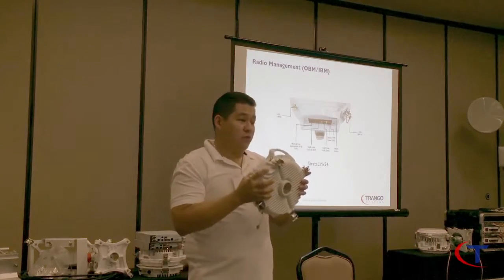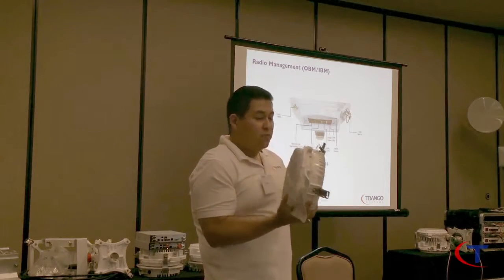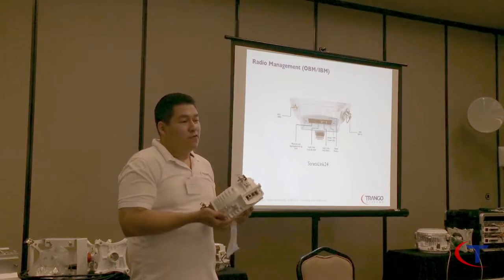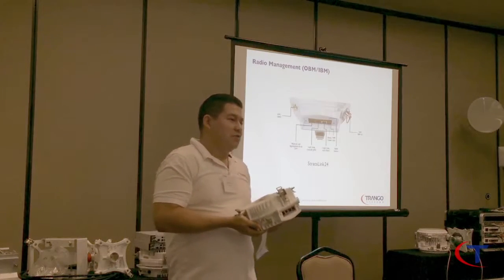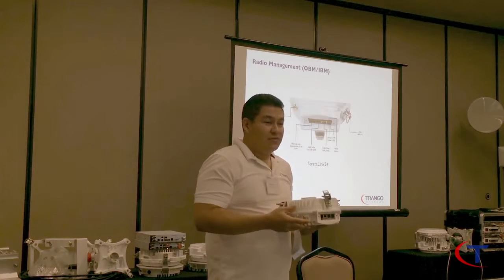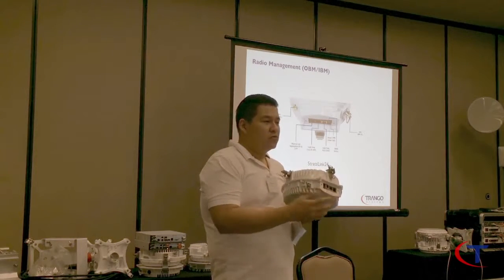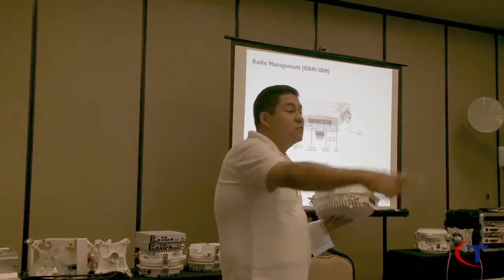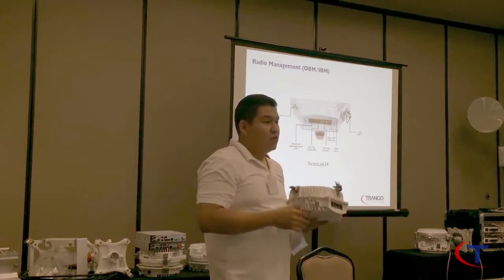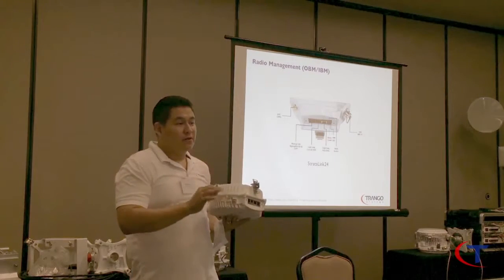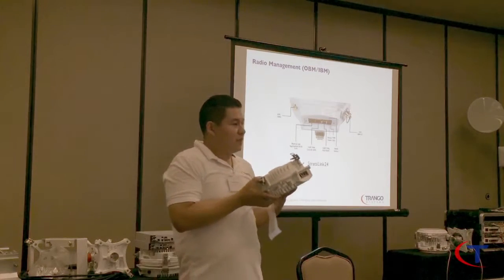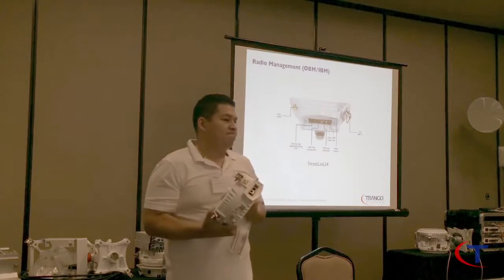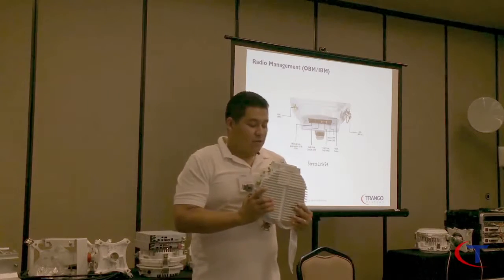It's only 24 gigs. One thing to know on this 24 gig radio: on the market, a lot of people tell you 24 gigahertz gigabit connection, yes, but they're Ethernet based. This one has a fiber port. So what does that mean? I can go further up on the tower, or I can go a longer distance from my NOC, from my shelter. You're not limited to that 250 or 300 feet Ethernet based. So you can actually put a fiber port and use DC power and take it all the way to 200 feet or 300 feet up in the air. So it's a really good rate.